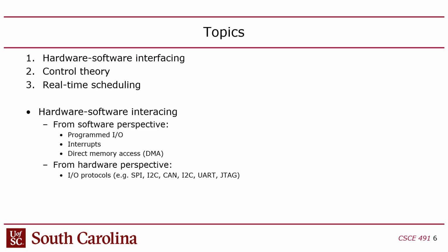So if you have a mouse, you're constantly loading the status register for the mouse to have the mouse tell the software what it's doing, right? How it's being moved, right? And likewise, if you're sending data to a frame buffer, like a monitor, you want to send data to your GPU, then you're doing a store and writing to a control register, right? But nowadays, there's not really a distinction anymore because you'll have some I/O registers that you can both read and write to, right?